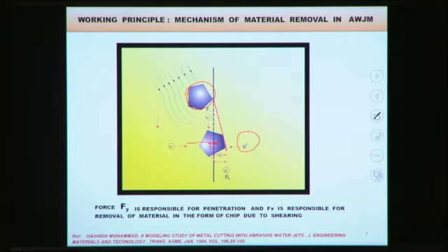So Fy helps in penetrating the abrasive particle into the workpiece surface, which is resisted by the reaction force Ry, and there is another force, Fx. This force Fx helps in cutting from the workpiece surface. So Fy is responsible for penetration and Fx is responsible for removal of material in the form of chips due to the shearing action on the workpiece surface.